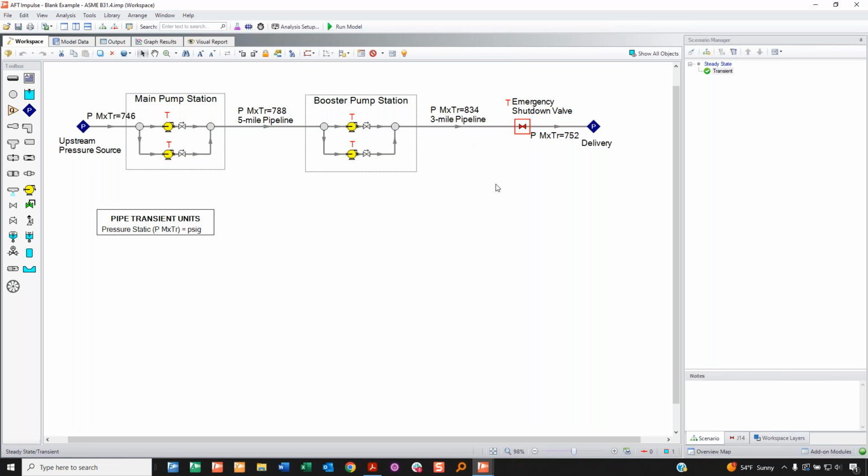That's probably no good. So let's do some quick math. If 700 is my design pressure, what's 10% above that? That's going to be 770, yes? Cool. You can tell the software to warn you anytime that pressure is reached and you're violating your own code. Sad face. So the way you do that is through a design alert.